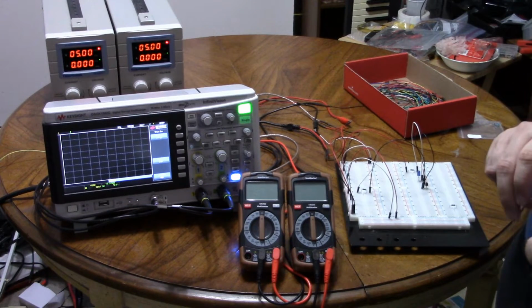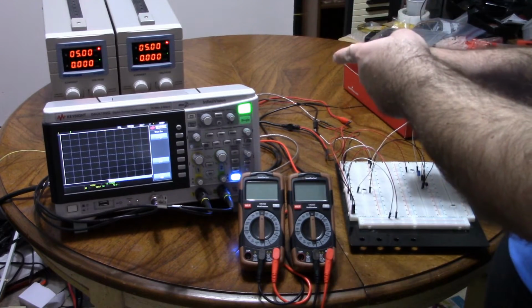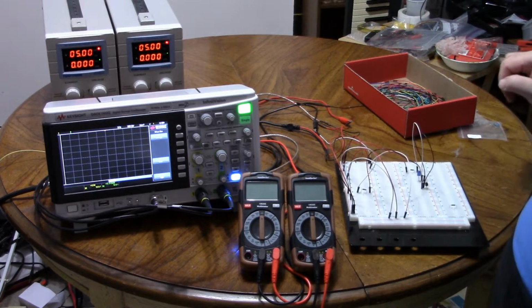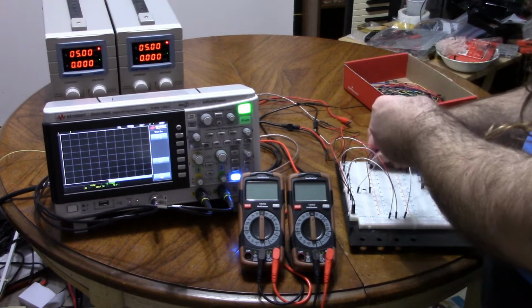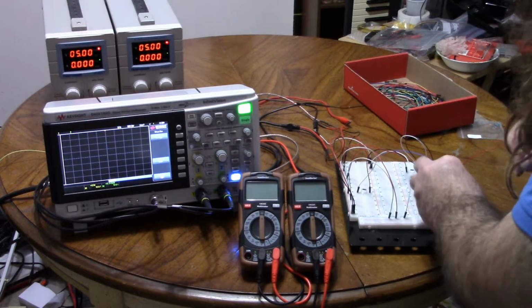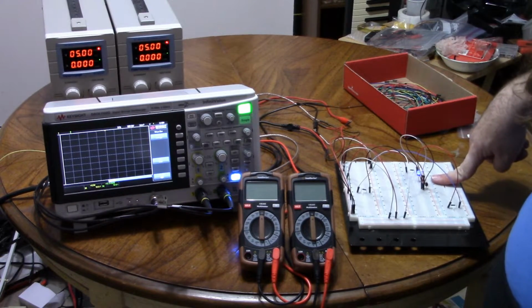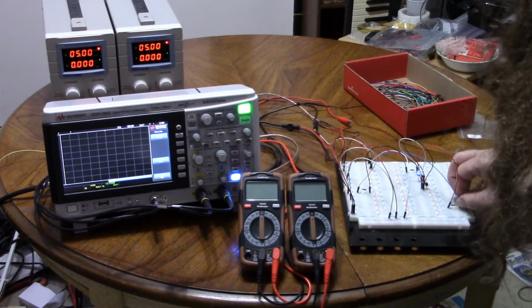And now for the negative power supply. The positive of the second power supply is going into the ground location, and the negative is going to connect to the emitter resistor, which I have to connect to the emitter, obviously. And once I do this, the LED turns on. Hopefully you can see that. Is it bright enough? Should be.